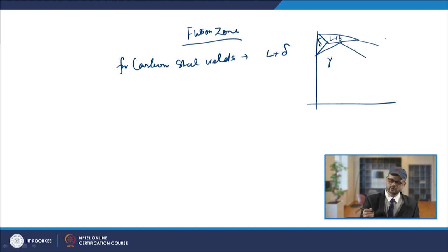Now, if you look at the figure, the schematic illustration of the microstructure of the fusion boundary zone, you will have this completely dark region, which is completely liquid. Adjacent to this liquid you will have very small grains showing, and then further away you have the coarse grains appearing.